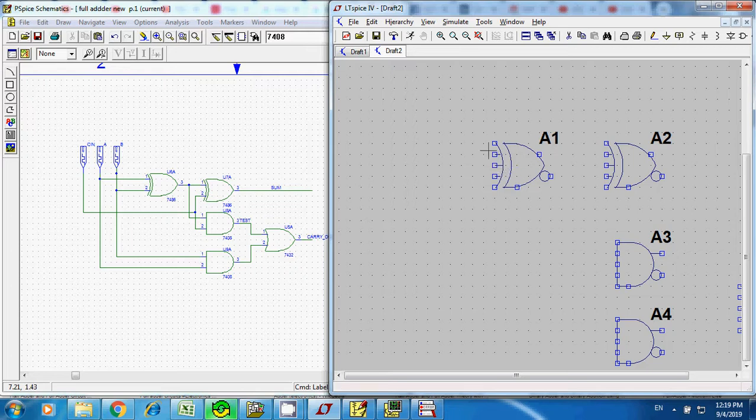I just leave some pins disconnected if not used. And again, you can take a look at this one here. For in the real circuit, if you pick up some IC, right, you cannot just leave some pin floating. You need to connect the rest of your pins to either ground or 5-volt supply, depending on what the gate is.